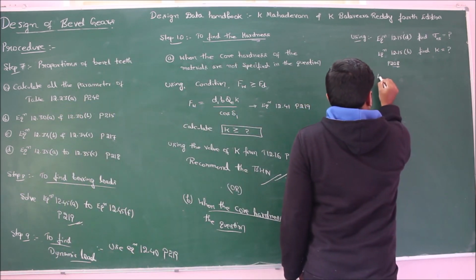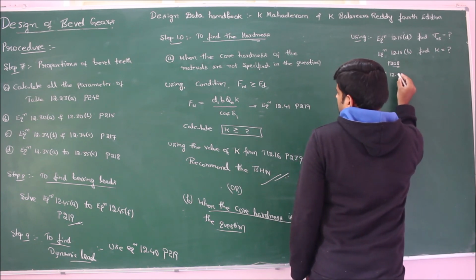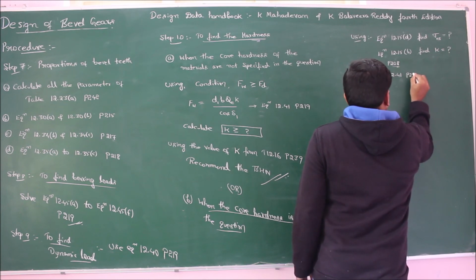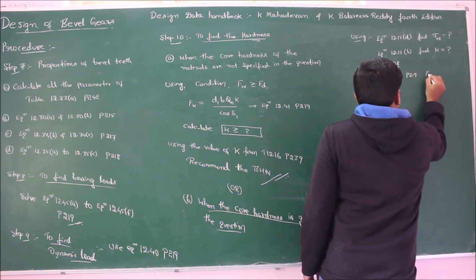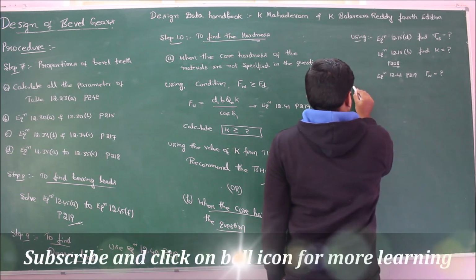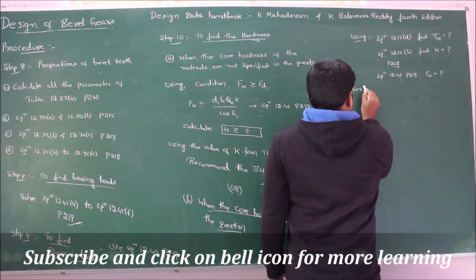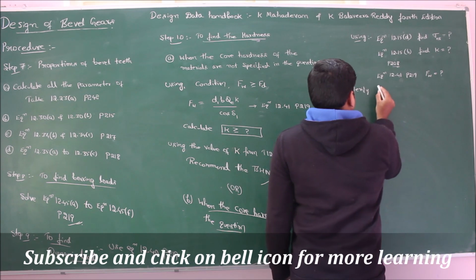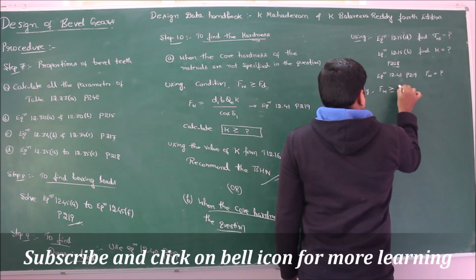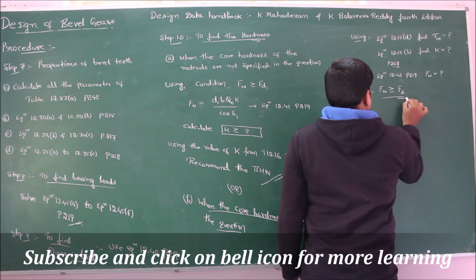So now, using equation 12.41 of page number 219, calculate the wear load. Now, verify whether Fw is greater than or equal to Fd.